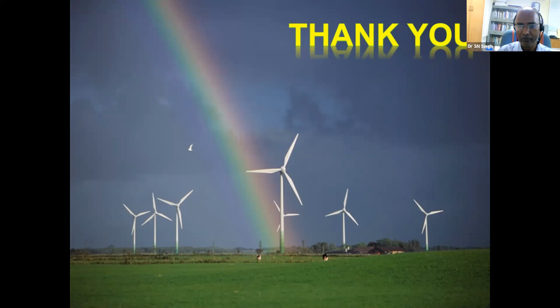But at the same time, with the help of these power electronics devices, we can control things. We can do something like voltage control very easily. But frequency control is very, very difficult, because it's related to active power. And once active power is not given by these renewable energy sources, then we have to meet it from the conventional sources.